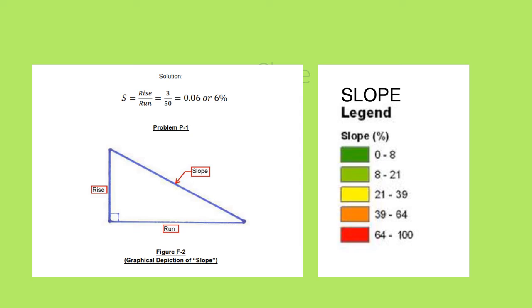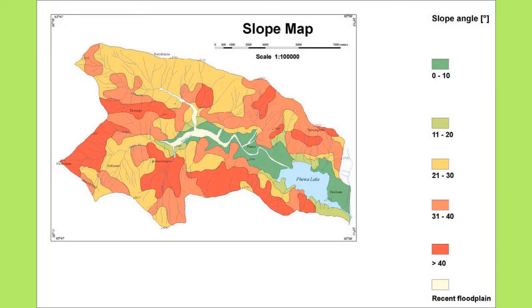Knowing the slope of the site is important in site grading. Doing site section helps, but it will not visualize the coverage of the slope in plan. Slope map will do that. It will determine on plan the extent of the slope as seen on map. This is an example of a slope map. The legend is not fixed. You can make your own legend according to your slope requirements.